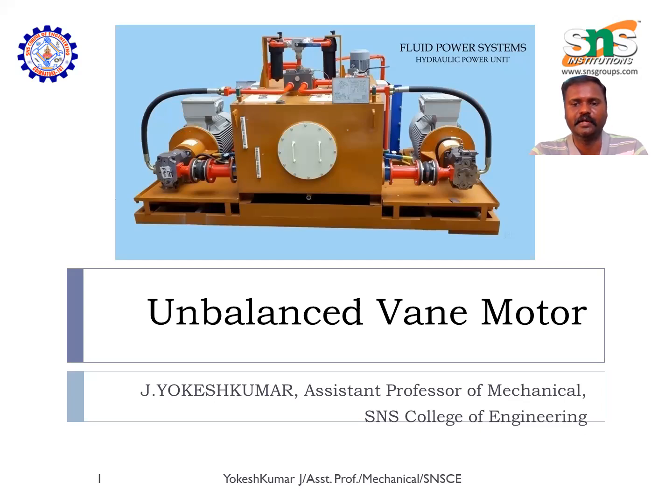So why is it called a vane motor? A vane is a mechanical element that is used in the motor, so that's why it is called a vane motor. Instead of gear teeth, we are using a vane. It is a structural member which is subjected against the spring force or hydraulic force, which will make an extension and retraction according to the rotation of the center rotor.